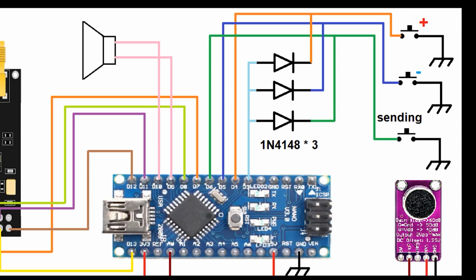This is the new circuit diagram I designed. When we press a microswitch, the interrupt pin is connected to the ground along with another pin of the microcontroller and we enter the interrupt function. Now in the program, we can define what to do. One of the microswitches increases the channel number, the other decreases it, and the third microswitch sends the sound.